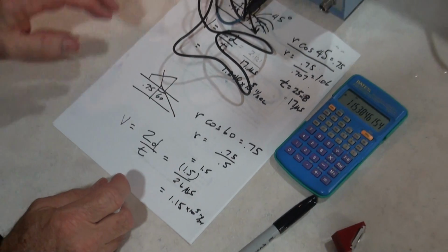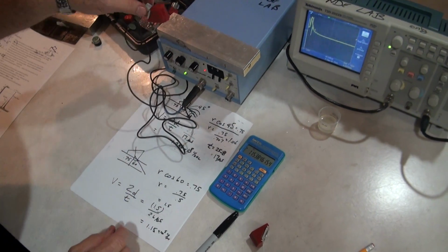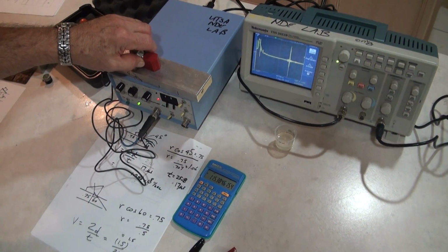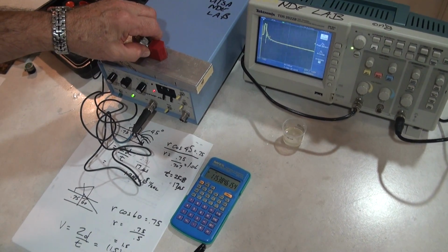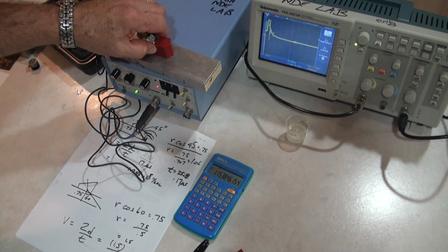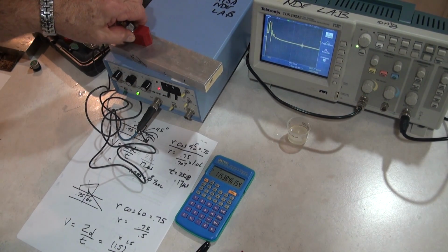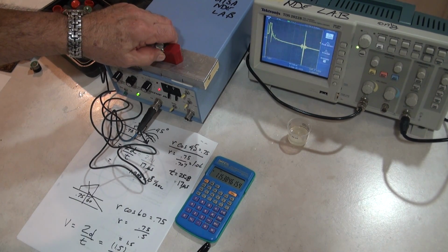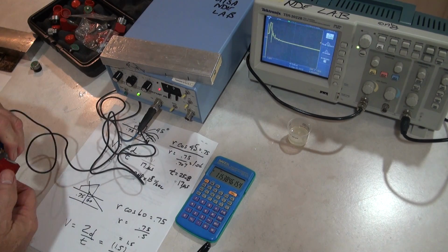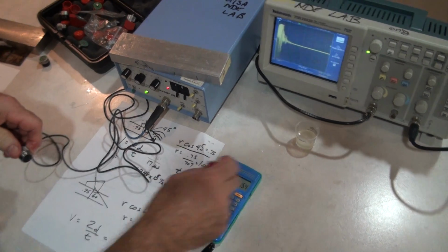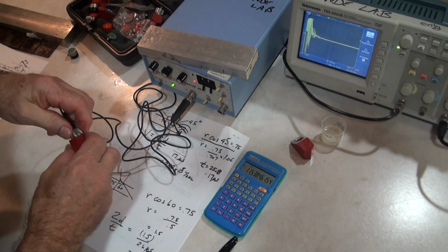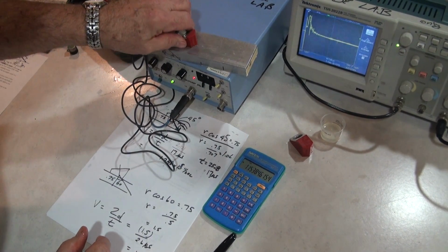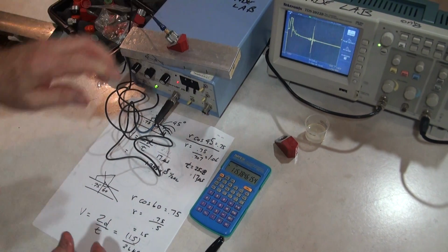Okay, so that's what we've learned today, which is how to use an angle beam. We look at an angle beam, and the signal's way out in time, and it's only there when we have a defect that's scattering off the corner reflector. If we use a different angle, this is a very high angle, so the signal is far out. If we use a different angle, such as 45, we'll see that happening at a different time, much closer.